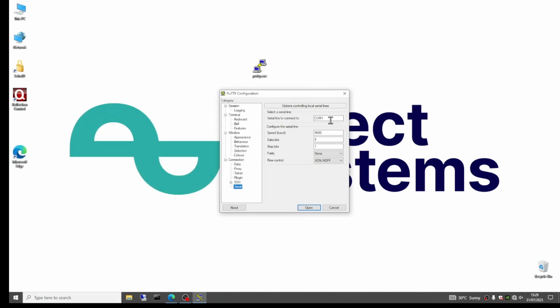So I'll close down Device Manager and go back to my PuTTY configuration. In the top box, I can now change that 1 to a 4 and then change the baud rate. All SQ cards use 115200, so we can put that in as well.